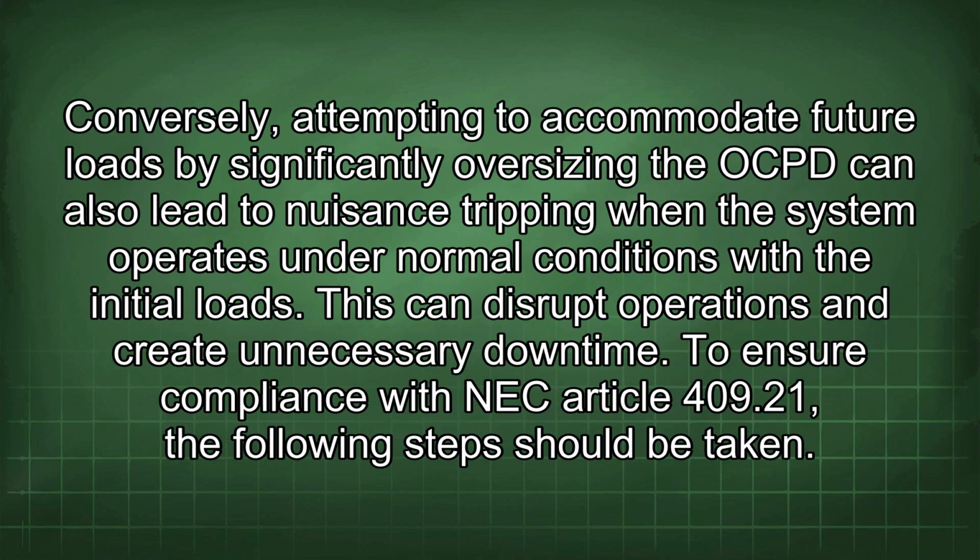Conversely, attempting to accommodate future loads by significantly oversizing the OCPD can also lead to nuisance tripping when the system operates under normal conditions with the initial loads. This can disrupt operations and create unnecessary downtime. To ensure compliance with NEC Article 409.21, the following steps should be taken.